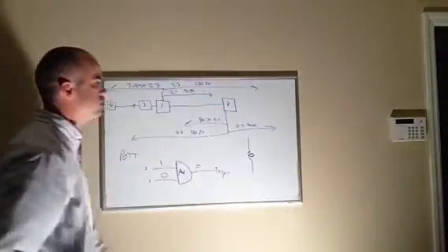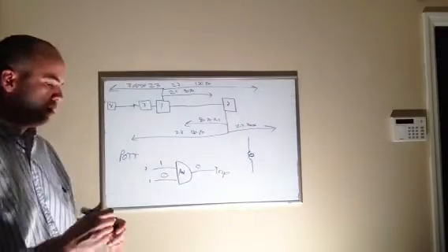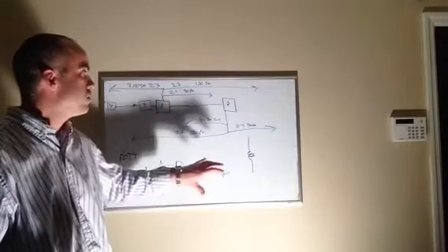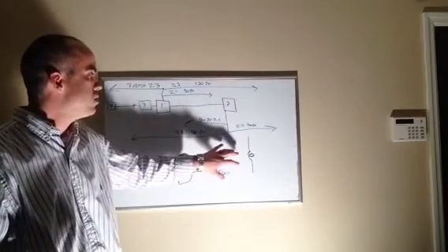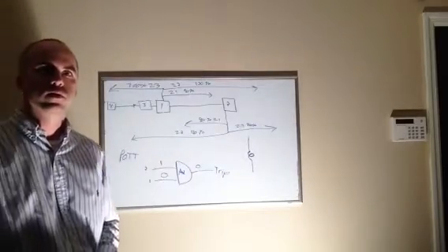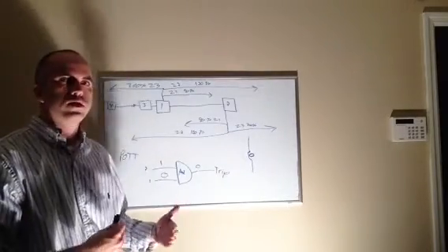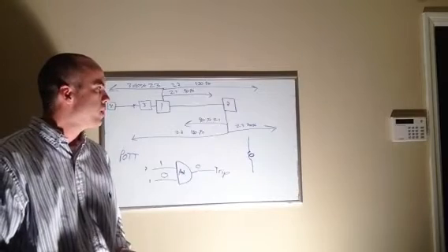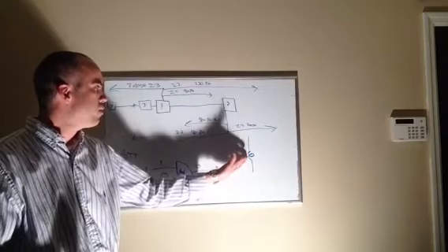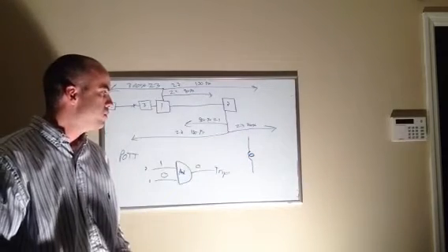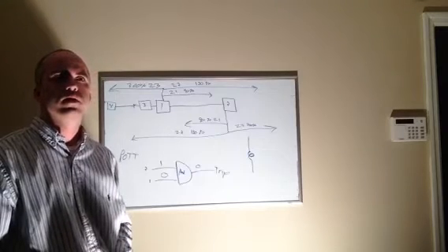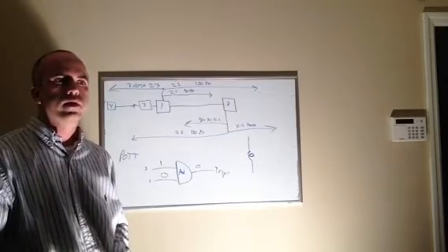Some kind of inductance sign, on the line coming into the substation representing a wave trap. And what a wave trap does is, because the communications is on that transmission line itself, it's a frequency filter that keeps the communications on the transmission line. So you'll see the power line wave trap. You might also see a carrier ground relay that would let you know that it's power line carrier.